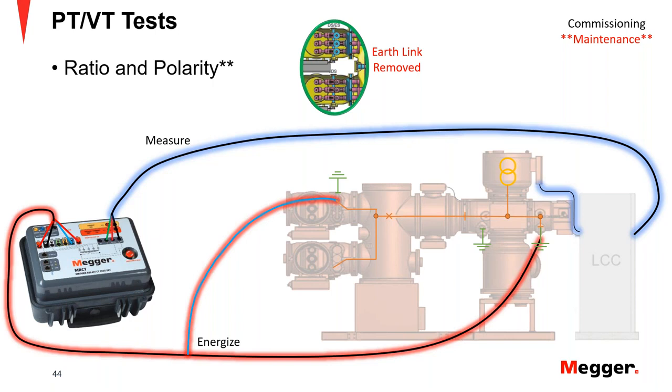opening the circuit breaker. And in the case of the CT, Paul mentioned when he discussed contact resistance, if you're doing winding resistance, that is a DC-based test for the CT. So remember to demagnetize the core.